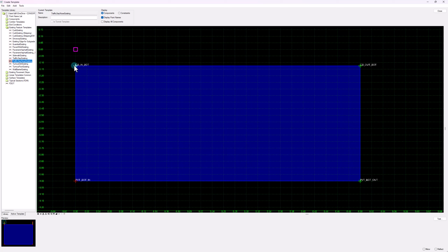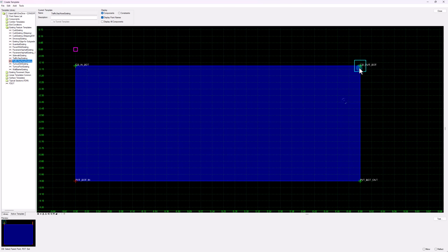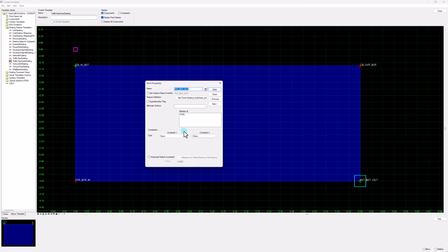And typically the way you handle components with depth is you always want to rule across the top and then rule straight down to points below. So if I go ahead and right click, add constraint, full constraint on this point to CB and bot, you can see it's just giving it a horizontal offset, vertical offset. And then this one is a little bit trickier. Not tricky, but we don't want to just rule it to one point.